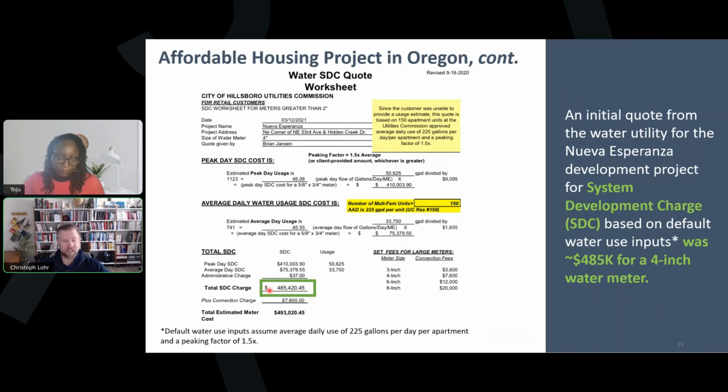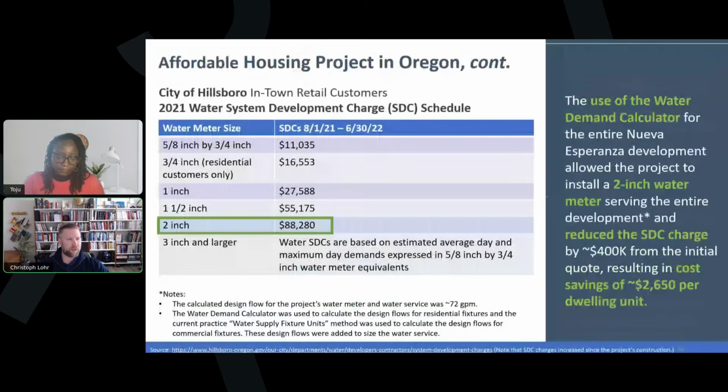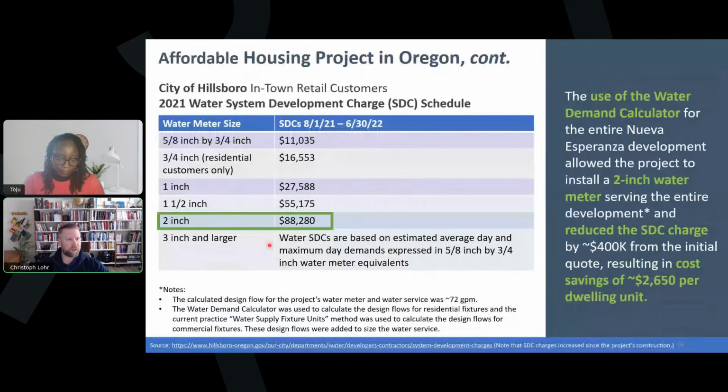We have a couple of slides that will show you a smaller multifamily project as we go through our example today. One of the things was that the meter size itself showed $88,000, almost $100,000 in savings, and that's not uncommon. As we talked about last time, the Alliance for Water Efficiency has a report that's worth looking at. It shows the ranges of what's out there from right sizing, especially going two or three pipe sizes down from 4-inch to 2-inch, and the water meter connections. It's going to have an impact.